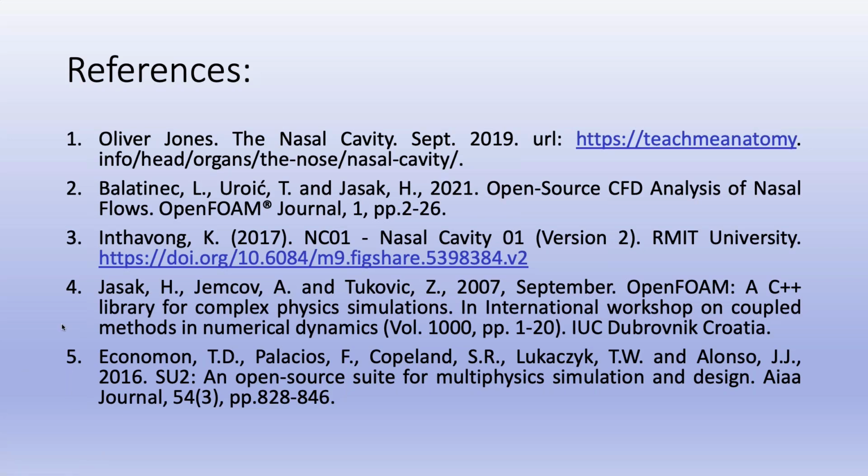This is Hrishikesh. The geometry is actually the cleaned geometry from the scan. These are the actual artifacts, but during cleaning of the geometry, some artificial artifacts have been created. The complexity has been reduced based on that cleaning, which makes the geometry somewhat less complicated. And yes, you are right, these are not the exact representation of the MRI scan. There are some locations where we have cleaned the geometry in order to make the CFD simulation possible. Otherwise, there will be singularities at some locations where there is high non-orthogonality or skewness.